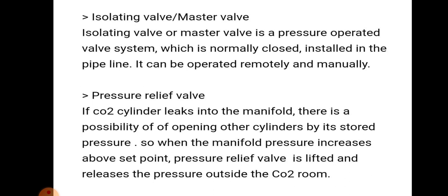Pressure relief valve: if a CO2 cylinder leaks into the manifold, there is a possibility of opening other cylinders by its stored pressure. So when the manifold pressure increases above the set point, the pressure relief valve is lifted and releases the pressure outside the CO2 system.